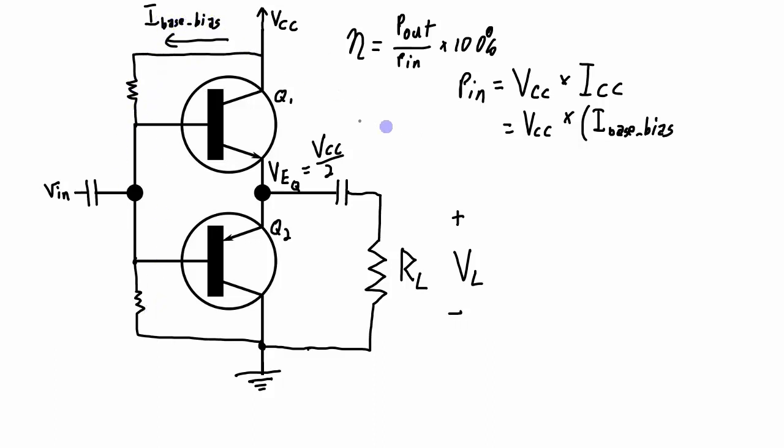And for this example, we're going to assume that this is so low as to be 0. Let's say these were 1 mega ohm resistors, so we're looking at microamps or so. Plus the average collector current. Okay, this is a constant. We're saying this part is 0, and so we need to look at what is this IC average.